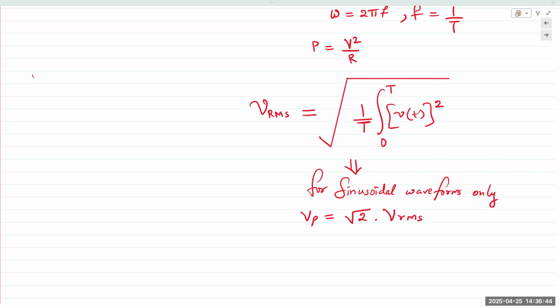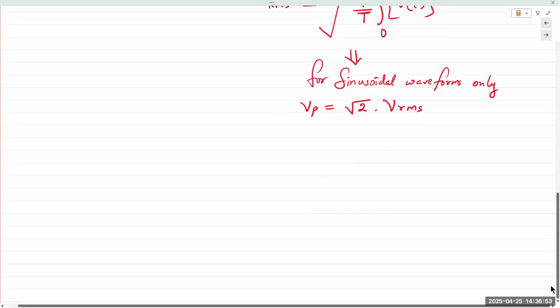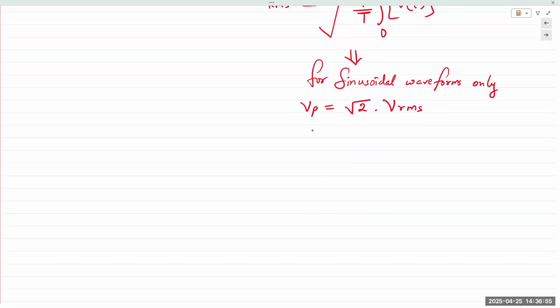All right, so for a sinusoidal waveform, the peak value is √2 times RMS. The ripple voltage output of the rectifier circuit, or even without, is always specified as peak-to-peak ripple. Okay, so ripple voltage is not technically a sine wave.